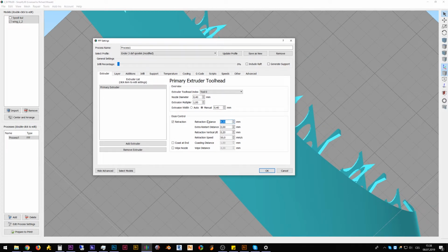This is just the amount of retraction. 0.5 or a number around this. This is a normal value for printers with a long extruder, with long extrusion, like Prusa. Printers with a short extruder, like Ender 3, CR10, and some Delta printers, will use this longer extrusion.